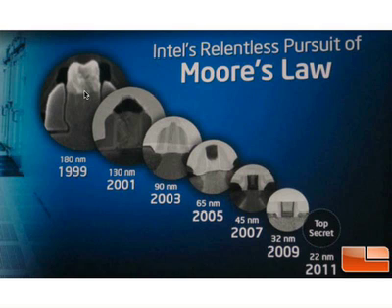You should be familiar with this now. You have a source, you have a drain, and you have a gate oxide and some gate, right? Okay, the gate length, which is the distance between the source and the drain, is scaled as you get smaller and smaller and smaller. It was about 180 nanometers in 1999. That is the distance from here to here, approximately. And it went down to 130, 90, 65, 45, 32.